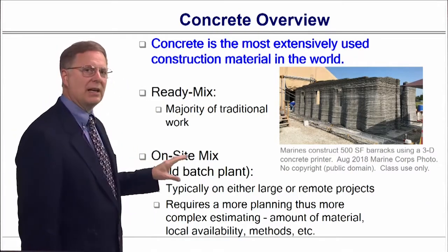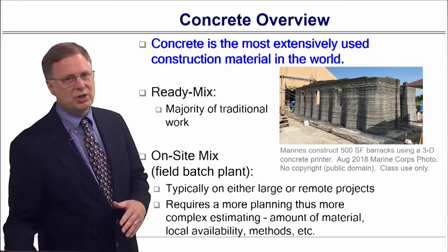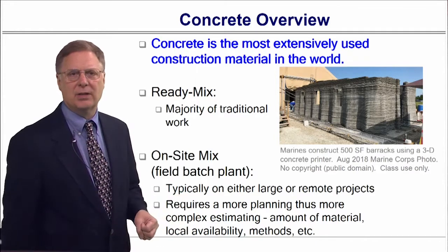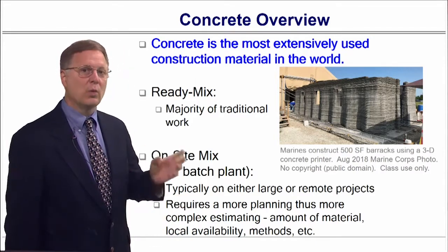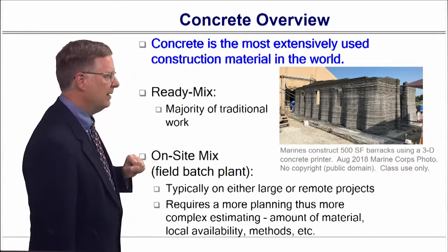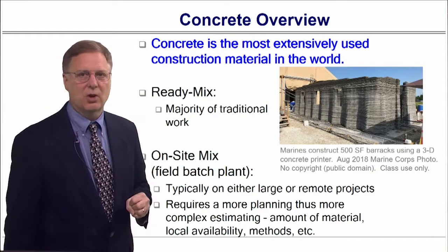There is a common occurrence: if you have a remote site, or a site with a lot of work going on, you might set up a field batch plant. Like on runways, you might see a field batch plant. Again, large remote sites. It takes a lot of planning to put one of those together, but it can be less expensive long term.